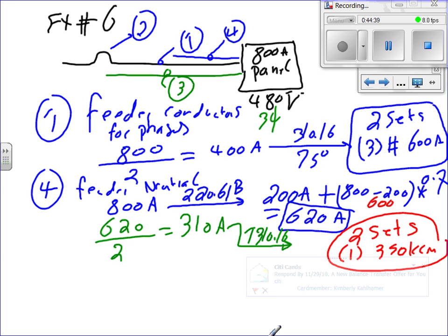Yeah. Okay. Now, your options, either you put the neutrals in one conduit, PVC only, phase A in one conduit, phase B in one conduit, phase C in another conduit, not commonly used in the industry, and parallel them. Or you put two conduits, and inside this conduit, most likely you're going to be paralleling them, guys, this way. That's the most common way of paralleling these boys.